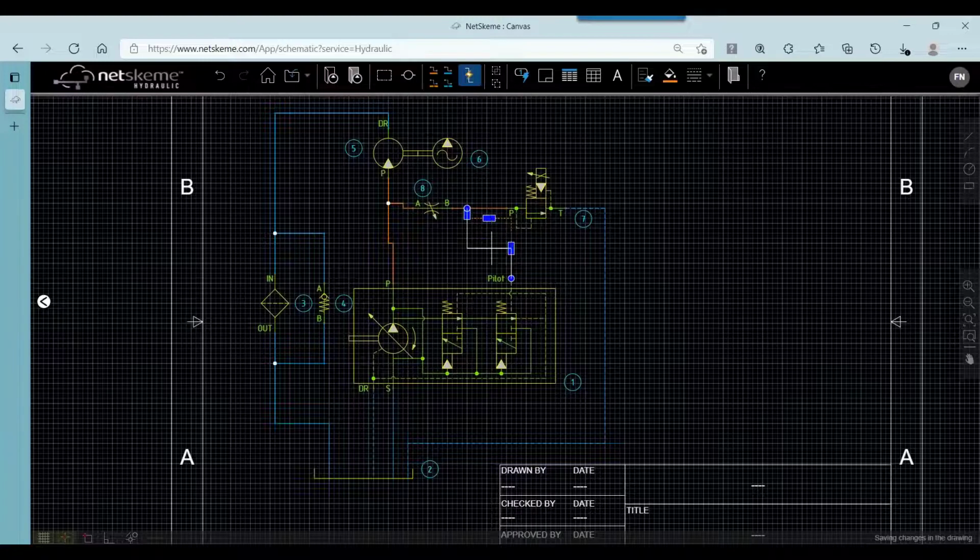So a little bit about this circuit. This is the entire thing. It is pretty small for this webinar, but this circuit is used in more mobile applications and can be used for crop watering. And basically with this relief valve and our pilot line here, you can determine how much water is going to be output up here. And it's set based on the components that you select.